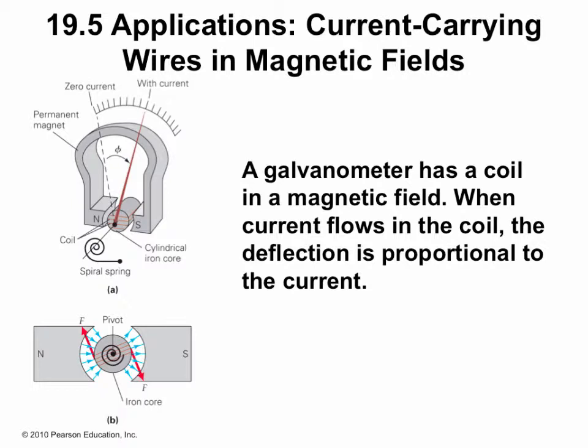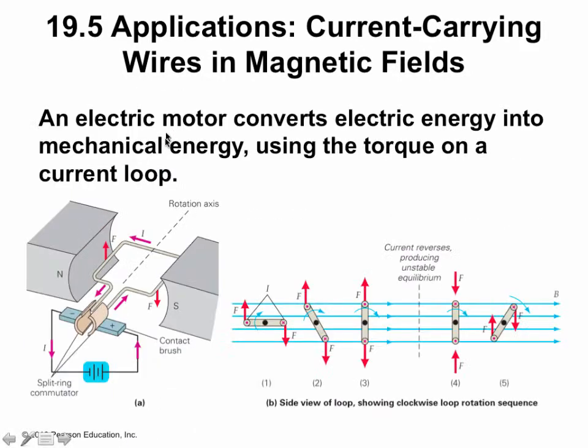Now, Mr. Adams' fancy multimeter has all this sort of stuff on a circuit board, and it just switches. I'll show that to you guys later. But basically what happens is as the current flows through the coil, it will have a force that causes this whole thing to turn, and then it'll measure current. Basically, it's an ammeter.